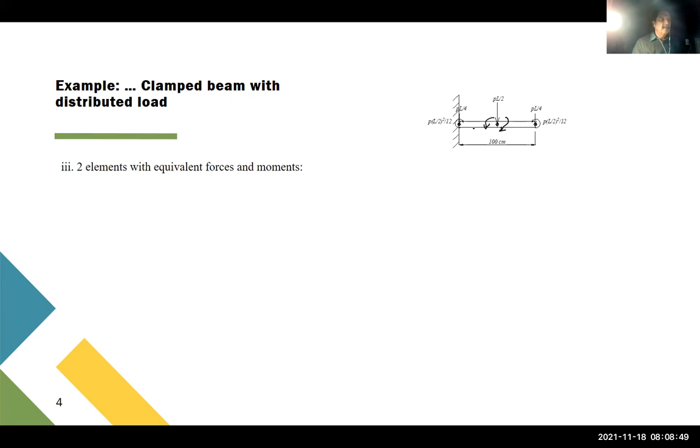Also, we have some force in this joint equivalent in this element and something similar for this other. These two values add up, and this is what we obtain. So we have a quarter, half, and a quarter of the total load.